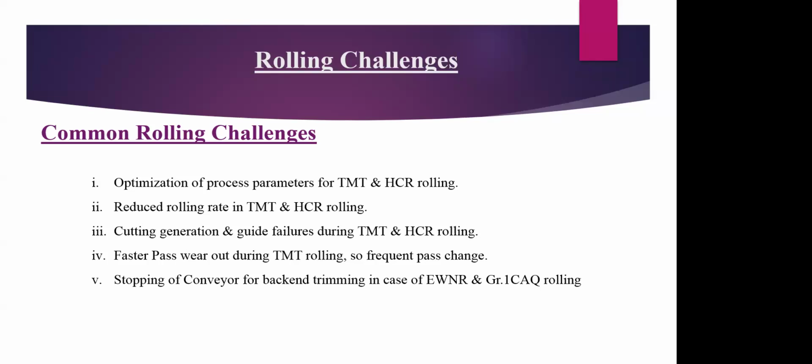Our opening of the TMT valve, it takes about 1.3 seconds from the time the signal is given, and we have optimized the process in such a way that the few turns which are laid from the laying head in the front, they are around 4 to 5 turns, and same thing again is done in the back end. When we are rolling TMT, that time we are also facing the problem in our roughing group, and we also have to reduce the rolling rate because our cooling sections are not long.